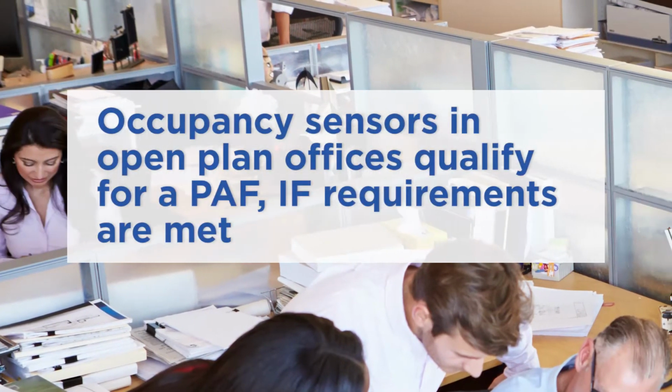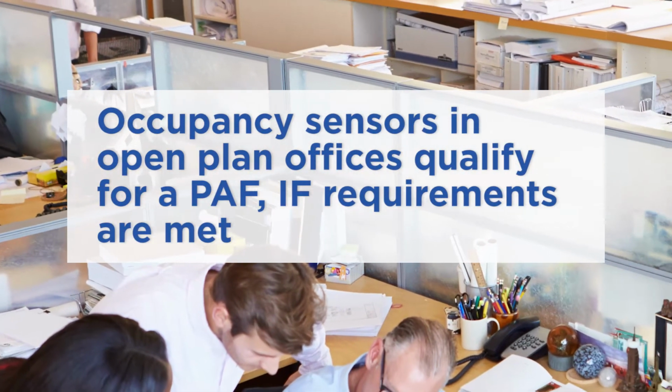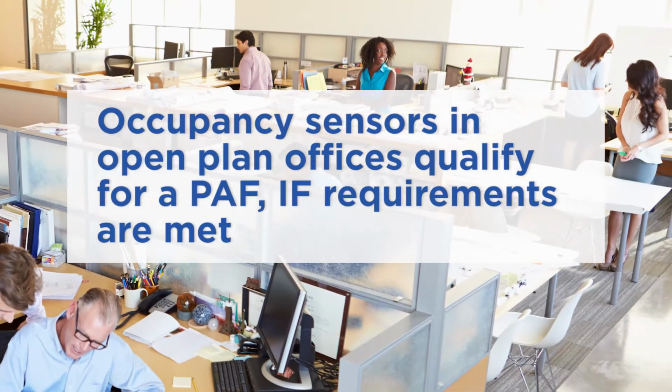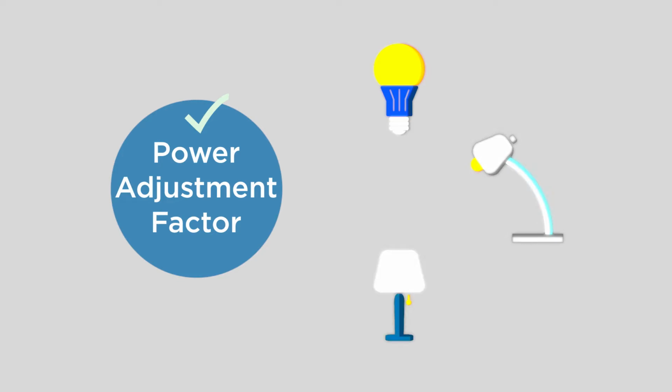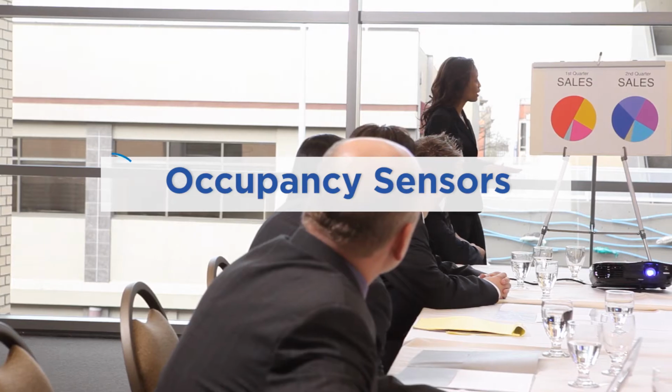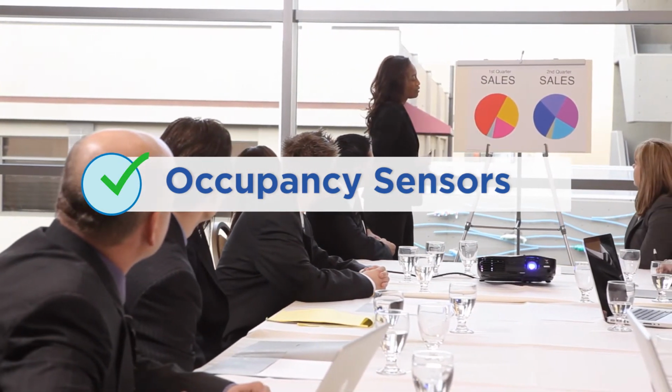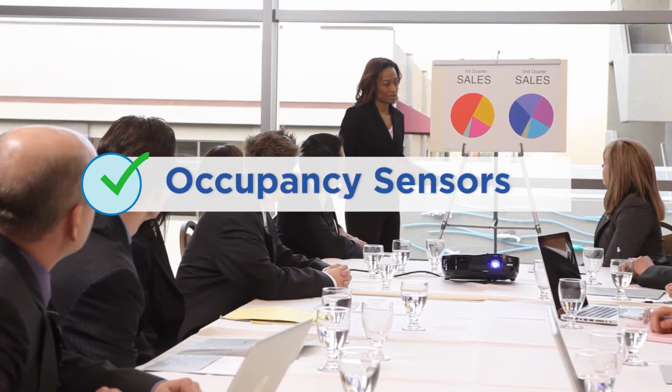Second, the use of occupancy sensors in large open plan offices qualifies for a PAF if certain requirements are met. Under the prescriptive compliance approach, as we have discussed in other videos in this series, voluntary use of certain lighting controls that go beyond mandatory requirements can give designers and building owners some flexibility to install additional lighting in a space. In large open plan offices, the use of occupancy sensors for general lighting above workstations is one such case.